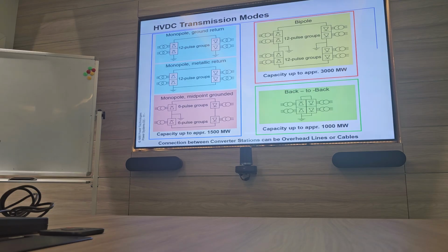Again, it depends on the distance. If it is a long distance, we need to go with HVDC only. So even with low power, if we have a lot of distance, we still go with HVDC. HVAC is also okay, but there are a lot of factors. HVDC is more controllable, and the power losses are less.